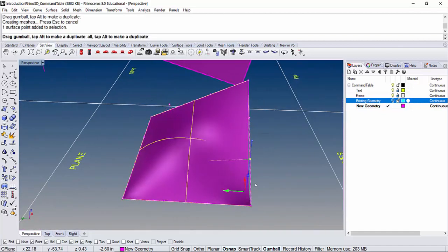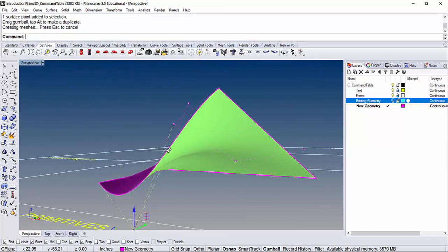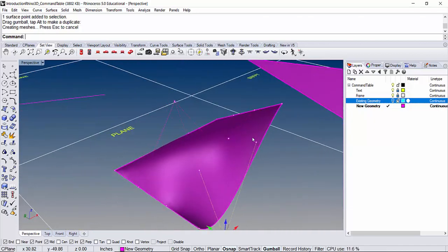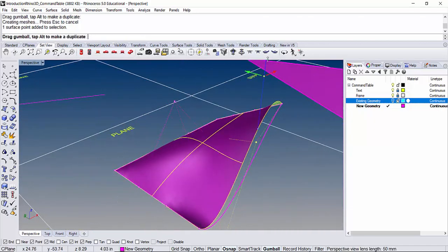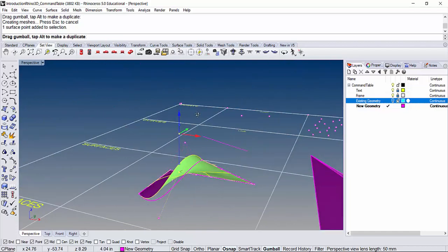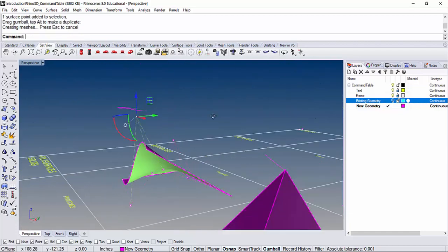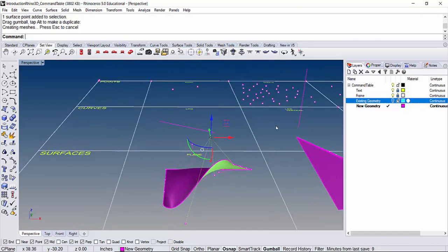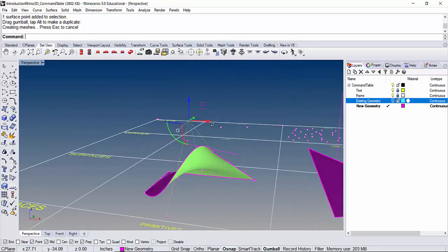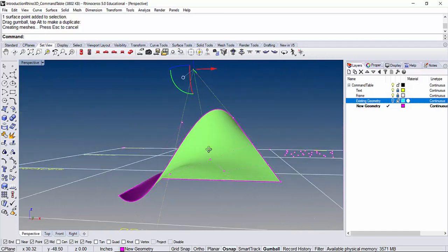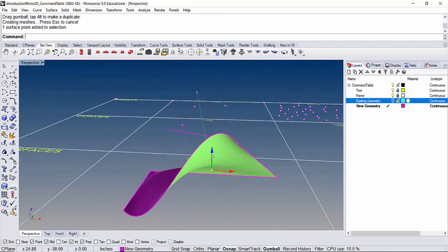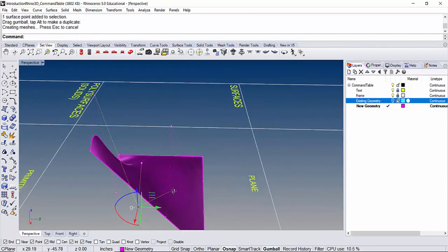So similar to the way that we had our 3-degree curves, now we're starting to have more variations here. And because this is a NURBS geometry, all of these networks, imagine it's encompassing your surface. When I'm changing one, this is a 3-degree surface, 2 other points are also being affected.